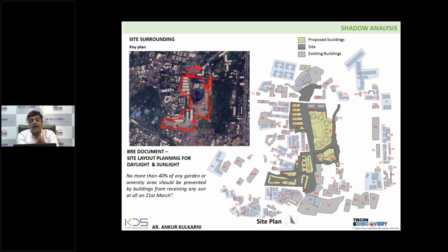of a high-rise committee, especially in the MMR and Mumbai region, where if your building height is more than 70 meters, then the first and prima facie requirement is that your proposed design should not cast any shadow for more than 2 to 3 hours on the surrounding buildings, because sun access is clearly considered your birthright.